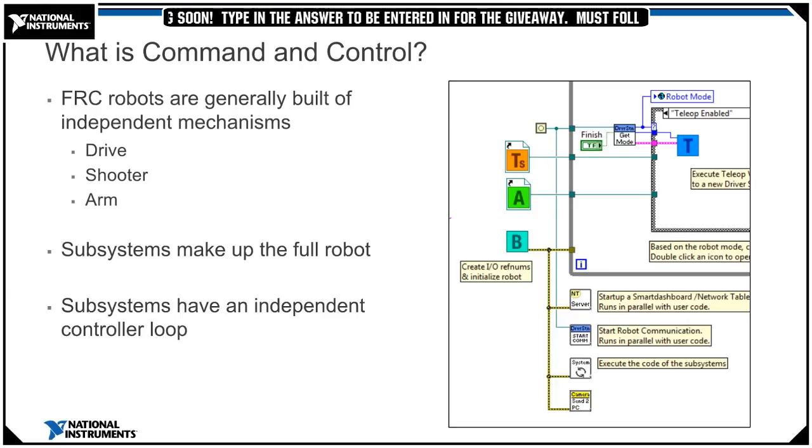The core idea behind command and control is that code outside of each particular subsystem can issue different commands that can change the overall robot's output, but should not directly change any outputs of each individual subsystem. So they don't really affect each other. The difference is subtle, but this means that outputs can only possibly be updated from one location in the project.